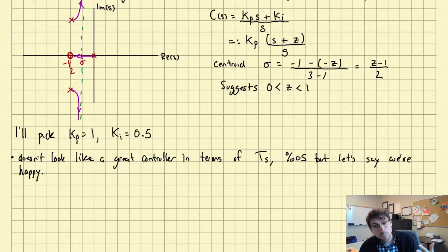Okay, so now we want to check whether or not we're satisfied with the controller, whether it works. Now remember, we designed the controller for the linearized plant, i.e. we approximated the nonlinear mass spring with a linear model and designed our controller. So what we do is we want to test whether it's going to work. And remember, one of the things is that this linearization is not going to be a very good model if we go too far from the equilibrium configuration. And in particular, if you apply too big a control signal, you might get far away from that equilibrium configuration.